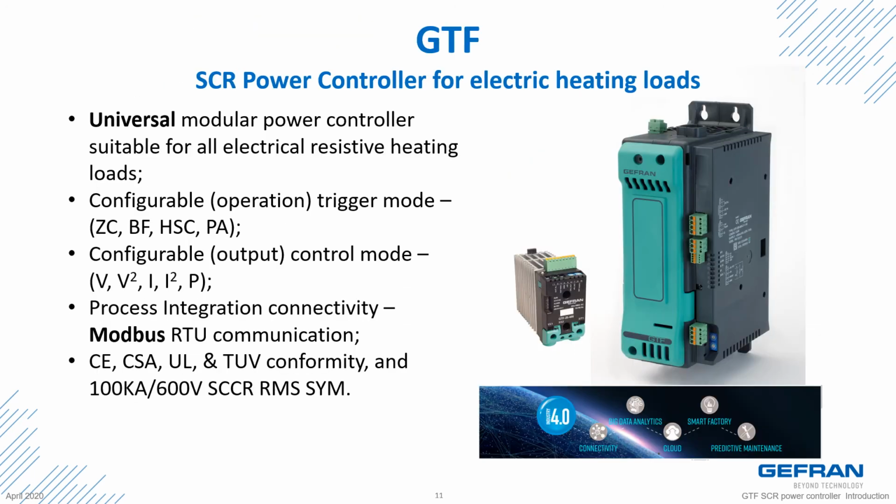Now let's talk about the GTF SCR Power Controller. It's a universal modular power controller suitable for all electric heating loads. It has a configurable operation or trigger mode capability, so we can control in zero cross, burst firing, half single cycle, and phase angle. It also has a configurable output or control mode, so we can control voltage, voltage squared, current, current squared, or power.